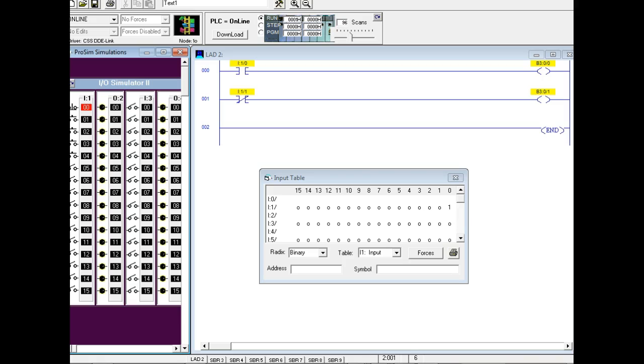So if you get into a PLC diagram and all the inputs are drawn as normally open, whoever programmed that used examine close. But if you see this on an input, not on a relay contact, don't get outputs confused with inputs. Outputs are either turned on or turned off, right? With inputs, you have to determine what is true and what is false. What would be the circumstances where you would change to examine open?